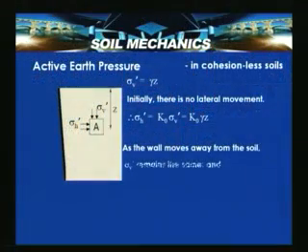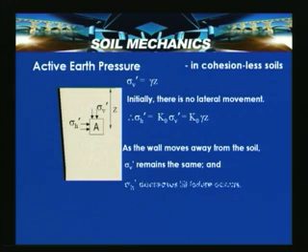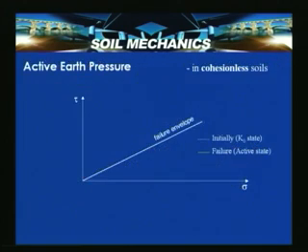Now, as the wall moves away from the soil, sigma V remains the same, as we discussed, because the weight of the soil which is actually participating is the same. So, with that sigma h decreases till failure occurs. So, what we have seen is that in the active state the sigma h decreases till failure occurs.